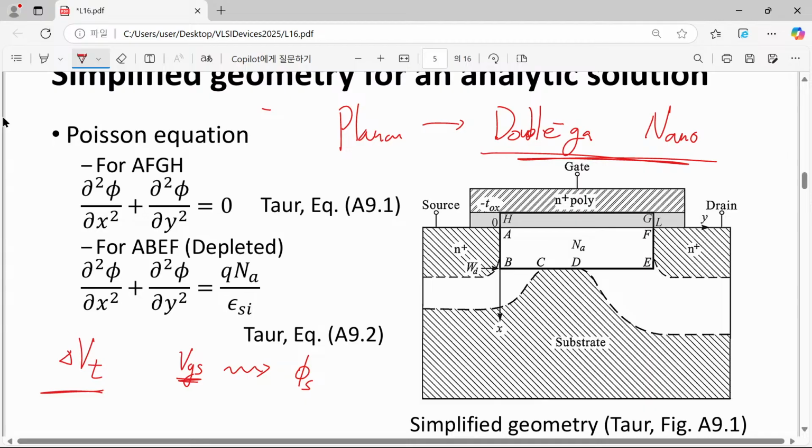And when we have gate voltage equal to threshold voltage, surface potential is quite close to 2 times band bending, 2 times the bulk potential. So therefore, the polarity is now inverted, and we can find the same amount of electrons which corresponds to the doping level, the acceptor density. That was the situation in our long channel device.